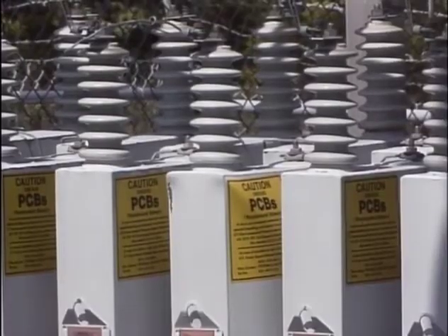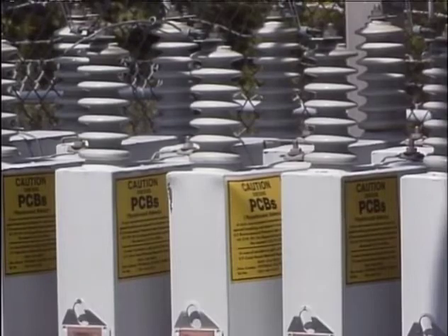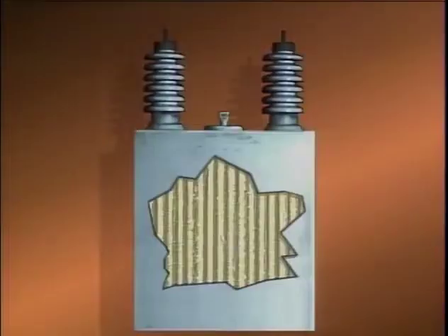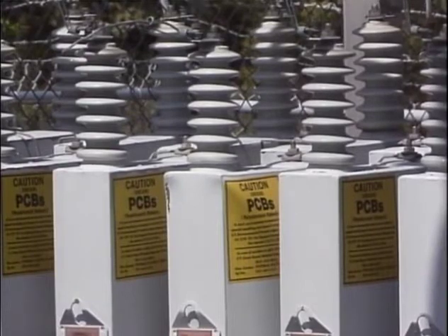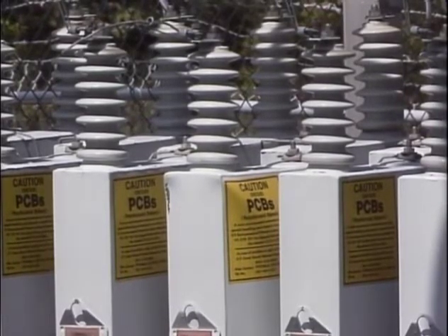Other precautions may be necessary depending on the condition of the capacitor that is being replaced. For example, a bulged capacitor should be handled with extra care. A capacitor bulges when arcing in the insulating oil creates gas and increases the internal pressure of the capacitor. An inadvertent bump may break the bushings or rupture the capacitor, allowing pressure to escape forcefully and possibly causing injuries. To protect the capacitor from bumping while it's being removed, it can be wrapped in rags.